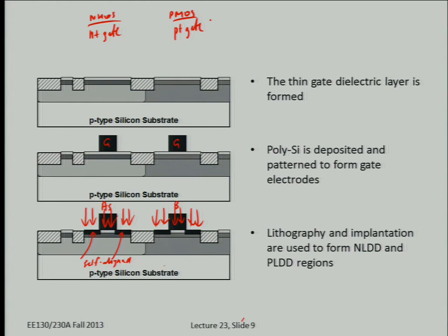Oh, okay, so if the gate material is a metal, well, if you implant dopants into a metal, it's still metallic, so it could potentially affect the work function of the gate, but I don't think people have actually studied that too much. But usually the effective work function of the metallic gate is not affected too much by implanting these kind of dopants. Yeah. Okay, good question though.